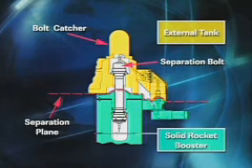The separation bolt half on the top that gets captured in the bolt catcher weighs about 31 pounds, and when it's traveling into the bolt catcher, it's traveling at about 65 miles an hour. So it's a pretty exciting event, and it's a very critical element that has to work every time with excessive margin to make sure that we don't have a serious debris event on our hands.